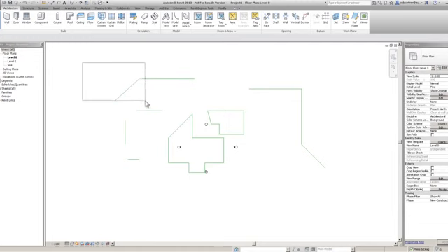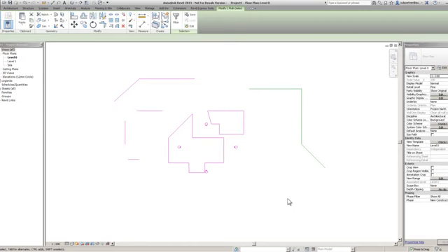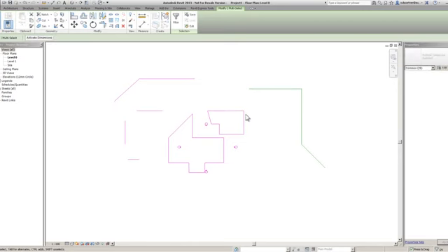It will only select, or in this case soft select at first, something that I am completely covering. Keep going, and you can see how that's working. I'm just going to drop it to there, like so. And you see how it selected these objects because the window completely covered them.